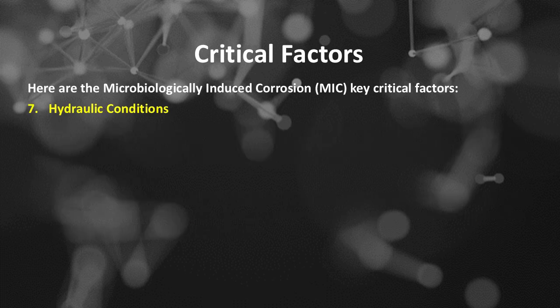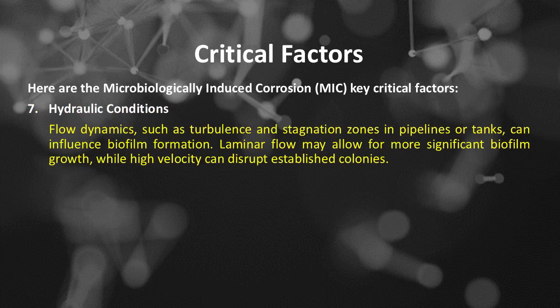Number 7 of the microbiologically induced corrosion, or MIC, key critical factors is hydraulic conditions. Flow dynamics, such as turbulence and stagnation zones in pipelines or tanks, can influence biofilm formation. Laminar flow may allow for more significant biofilm growth, while high velocity can disrupt established colonies.